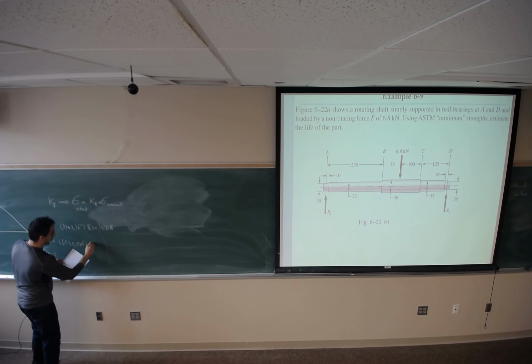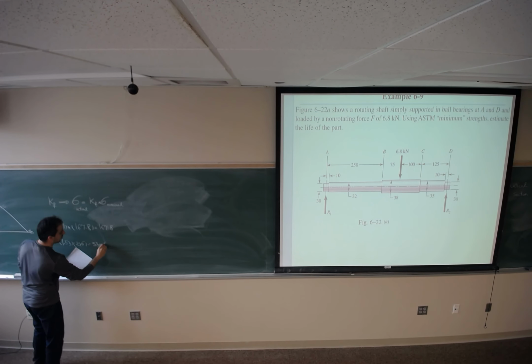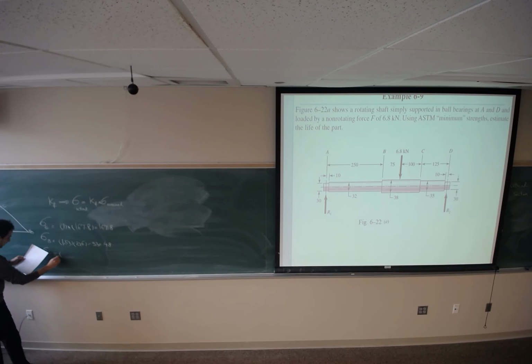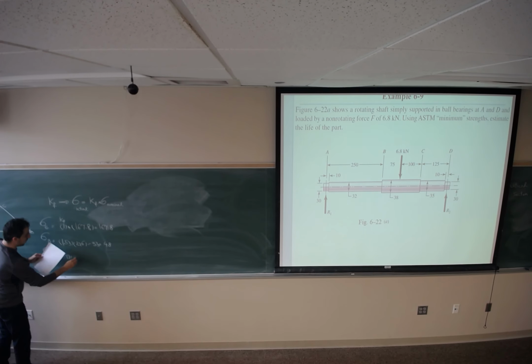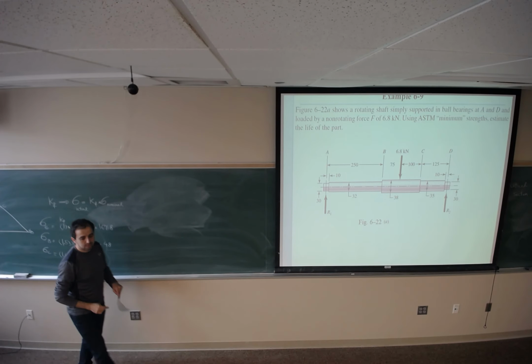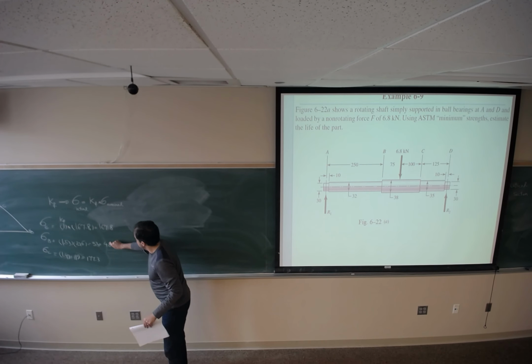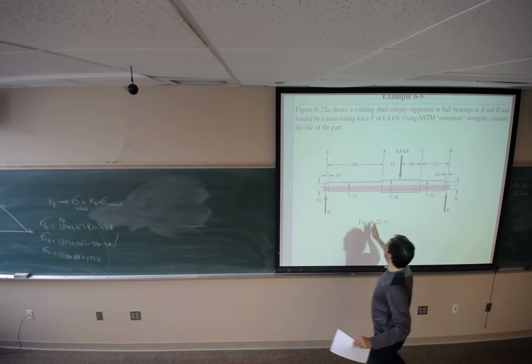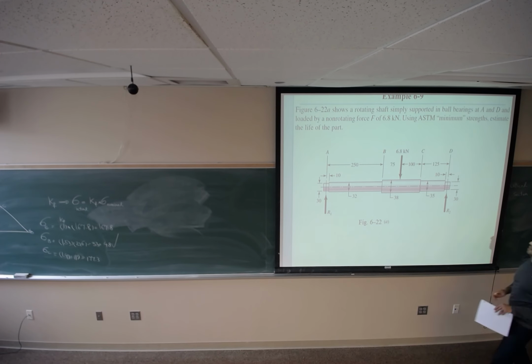We got 330.48 megapascal, and for this one the fatigue concentration factor was 1.49 times 119, we got 177.3. So then we compare these three. This stress is the highest, so section B is going to be the critical section. So we should do the rest of the analysis for that section.